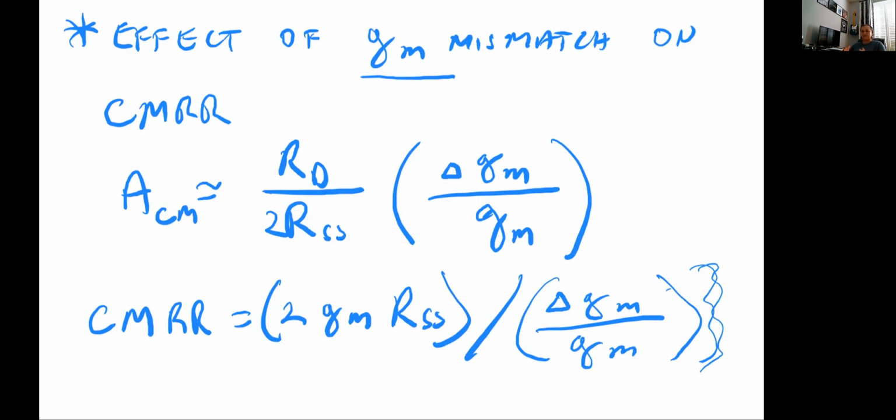So at some point, we have to convert from differential to single-ended. And the big drawback of doing that is that the common mode rejection ratio is reduced greatly, unfortunately. And that's for very high-end, high-precision type of applications. Although they are more expensive and complex, you have a fully differential op-amp that has a differential output.